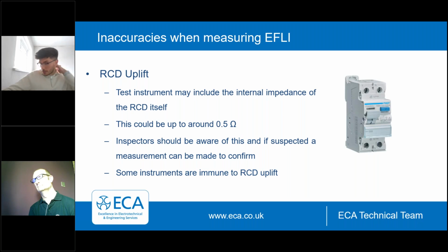It's worth pointing out, though, obviously technology is always evolving, and for some time now there have been some instruments around that are immune to the effects of RCD uplift. So we encourage you to consult your manufacturer's data, as your instrument itself may be immune to the effects of RCD uplift. And I think that's probably the first time of many today that we are going to encourage you to consult your manufacturer's data with the requirements and performance of your test instruments.